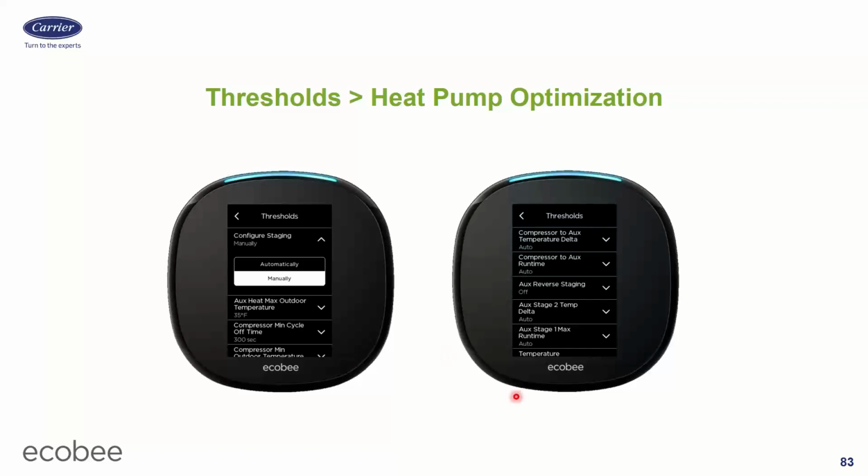And then additionally for the heat pump, because we looked at it before on the furnace and AC side, now we're looking at it again because it's a heat pump. So I pick my max outdoor temperature, but if I had this configured for manual, I could also pick the delta between running the compressor and the auxiliary. If I have more than one stage of auxiliary, then I can enable reverse staging on the auxiliary heat as well, as I've already done it on the compressor. So all those same kind of things I could do on the compressor and on the auxiliary heater.